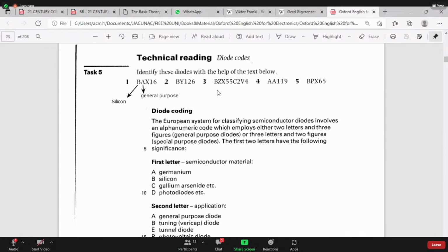Number 3, that is the one that I wanted to write, because this diode is a silicon, but the letter Z marks that it is a Zener diode. And you can notice that because there are more characteristics. So this is a Zener, silicon Zener. And if you check, you have the letter C. The letter C indicates some tolerance.